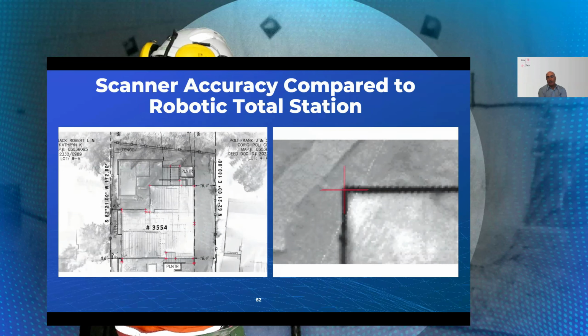And even after all these years, that thick line, this is the correct survey, not that 1-point survey, because the reality is that the wall is not straight, it's not 100% straight. If I would get 10, 15, 20 shots vertically on top of each other, I would be in the same location, very close, because the forms are not straight, the walls are not straight.